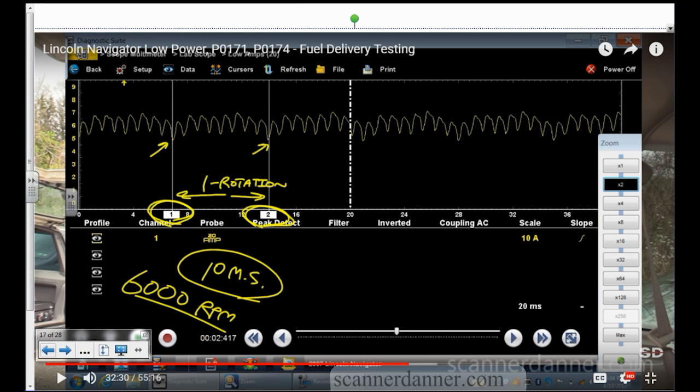The pump was running at 10,000 RPM, and on that particular car it should have been about 5. So the pump was running double the speed because when they put the pump in, they wired it backwards. So the pump was sucking rather than blowing. Can you picture that, a pump that's really pulling air from the front? And it's very easy for the pump to spin because there's no fluid there, as opposed to spinning the other way. So anyway, pump RPM can be beneficial.